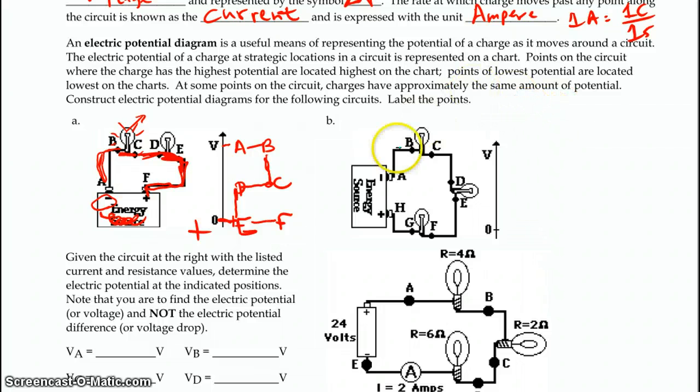Okay, so now notice this one, they have A at the negative. I'm going to actually therefore start at that same point that we had before. So here's our start point. A, again, the negative terminal of the battery is where we have the highest potential. No change between there and the wire B. Now this time there are 1, 2, 3 places where we can lose the energy.